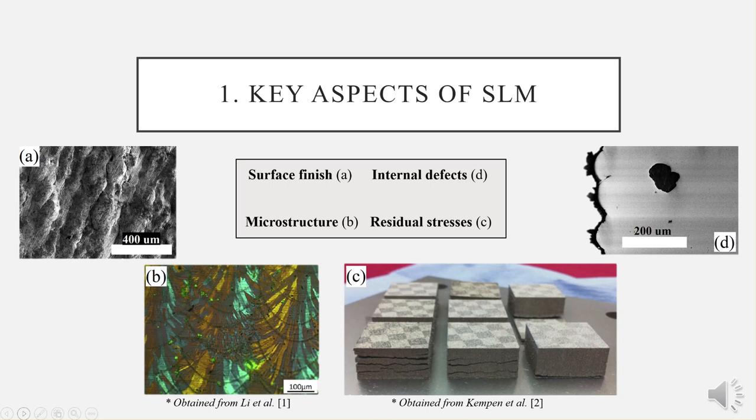Third, the successive, very localized heating and cooling cycles imposed by the metal-laser interaction result in incompatible thermal strains that need to be accommodated in the form of residual stress or, in the most severe situations, macroscopic delamination or cracking of the specimen, as depicted in Figure C.